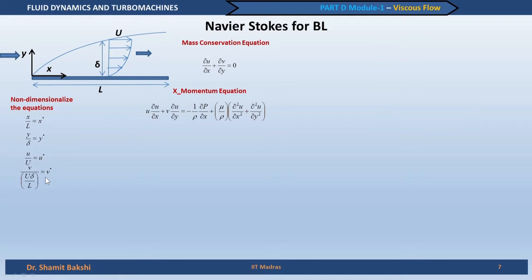Now, I think we are all set to actually write this equation in terms of the non-dimensional variables, that means x star, y star, u star and v star. Of course, we have not addressed p. So, p has to be non-dimensionalized with rho U square, the same unit, because explicitly there is no pressure term appearing here. So, we just use the same dimensional quantity rho U square to non-dimensionalize p and name this as p star. When we non-dimensionalize an equation, every quantity has to be non-dimensional. So, that is important. Now, let us replace the quantities like velocity, pressure, etc.